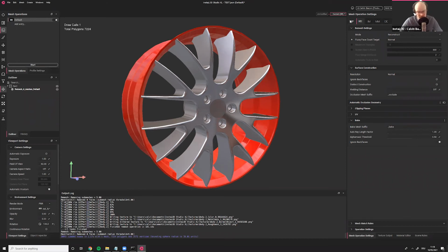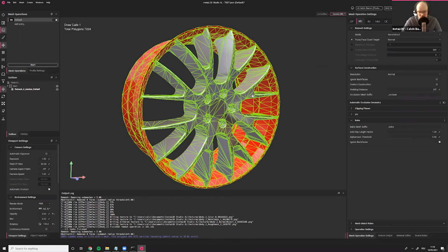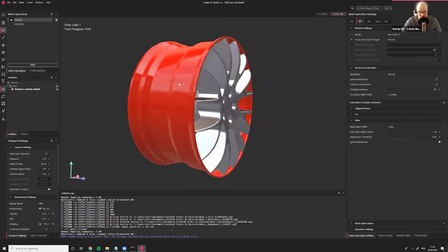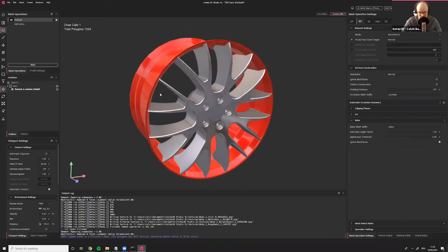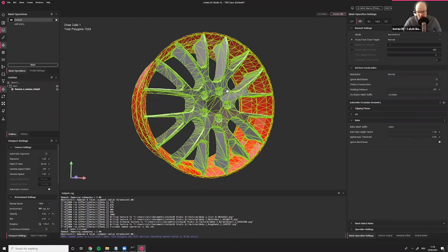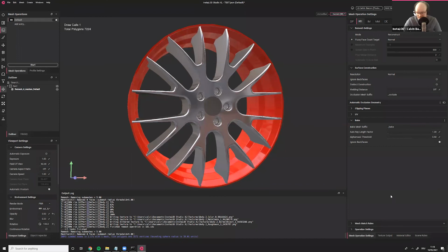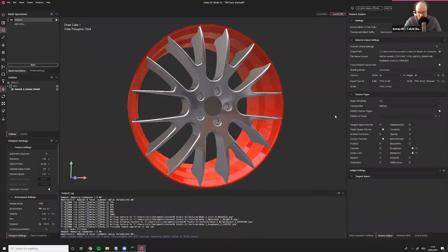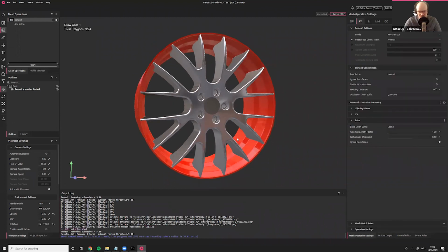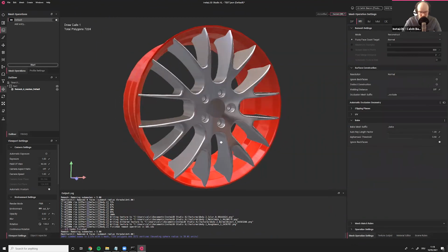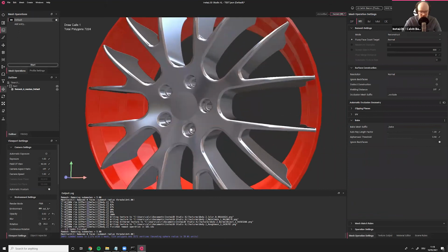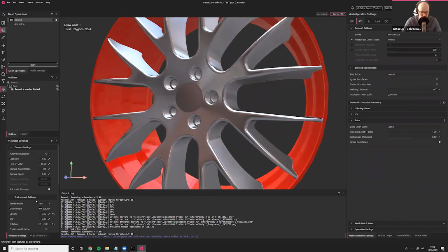Remeshing, as we've seen today and as we've seen here, does a full reconstruction, right? So super low poly, and yeah, that's that. This remesh took really long because we've been baking 8K textures. Normally I would do it on 2K and then it goes much faster. That's normally done within like a minute maximum. But because we've baked 8K, it took so long. But you can see, right, even with like a 90% reduction of this remesh, we've got really good looking results.